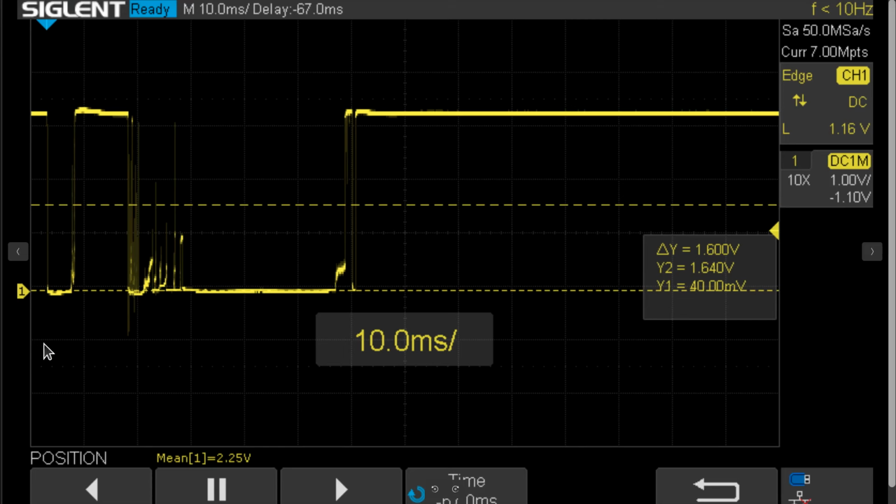This will be completely thrown away, as will all these spikes. Oh, it went 0, but not long enough. It went back to 1. Okay. Oh, it went to 0. Okay, start over again. And it'll bounce back and forth and back and forth. And finally down here, it'll say, aha, it has gone to 0. It has stayed 0 for an acceptably long period of time. And maybe way over here will be the point in time where we actually see, okay, bang. This is when it went from 1 to 0 on the output of our synchronizer.